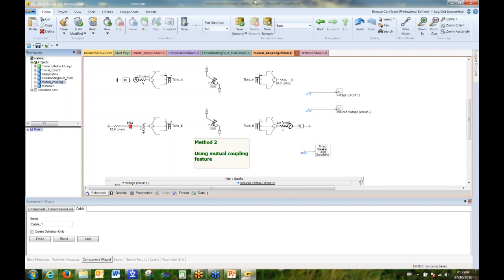So another question is, how do we know the operating temperature of the cable? Well, there are some publications. If you go into the CIGRE working group C4.502, usually 90 centigrade is used, but some publications suggest 70 centigrade. It depends.